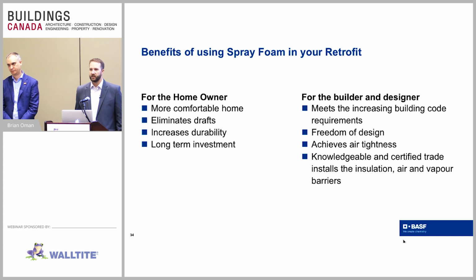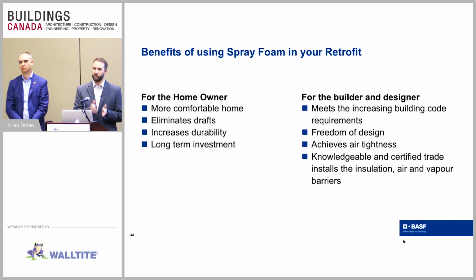Yeah. Sound transmission is airborne transmission or structural transmission. So it's an air barrier, so it stops the airborne sound transmission really well. But because of the density of the closed cell, those structural vibrations can work their way through and vibrate through the product. The open cell, as Chris said, is closer to a mineral wool or a fiberglass or something like that, where it's able to absorb that sound wave and deaden it so it doesn't pass through nearly as much in a structural manner.